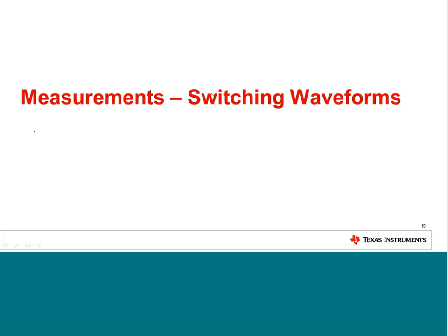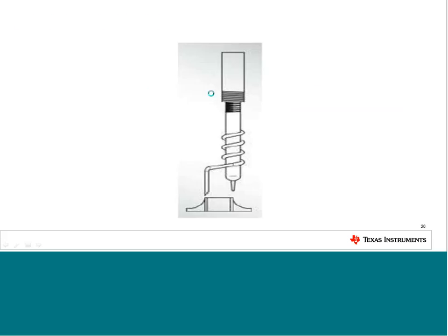When you look at the switching node, and this is a measurement you do to assess the reliability of the circuit, you need to consider the highest frequency you want to measure. And since you have rise times in the range of a few nanoseconds, your frequency is in the range of several hundreds of megahertz.